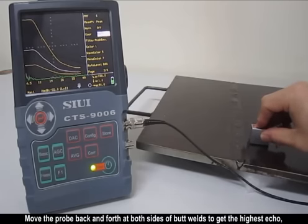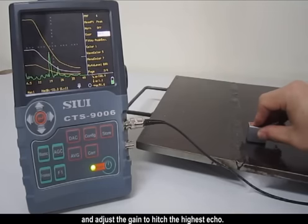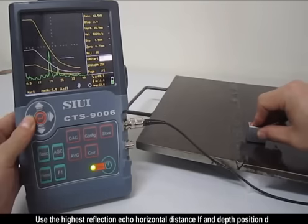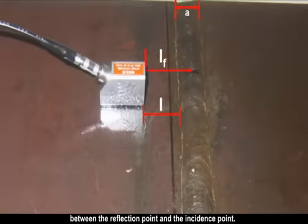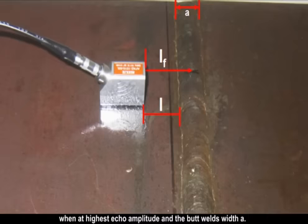Move the probe back and forth at both sides of the butt welds to get the highest echo, and adjust again to hit the highest echo. Use the highest refraction echo horizontal distance LF and depth position D to determine whether it is a defect. The method is as follows. Determine the horizontal distance LF between the refraction point and the incidence point. Use the ruler to measure the distance L between the probe flank and the weld edge at highest echo amplitude, and the butt weld width A.